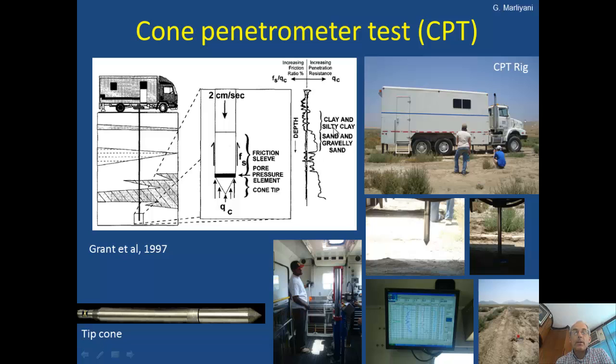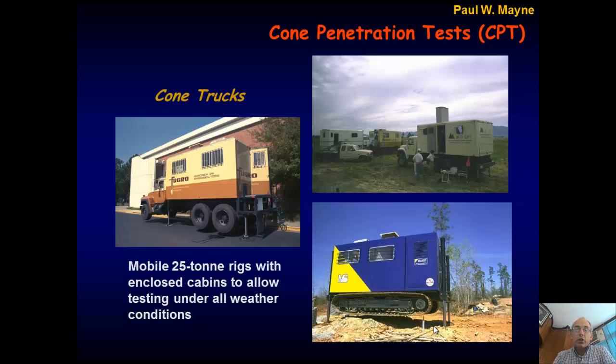So it's fairly routine to interpret these friction ratio profiles in terms of the underlying lithostratigraphy, the changing rock types. The nice thing, as I said, is that it's a fairly standard approach. It can cost some expense to rent the machine, but once you have it, you just go. Usually they have onboard interpretation, so it's easy to see the results right away, and you can try again if there's a problem. There are different trucks, and in many places there are companies that you rent the truck from. They provide the engineer and the operator, and you just say, okay, go, let's do a profile.